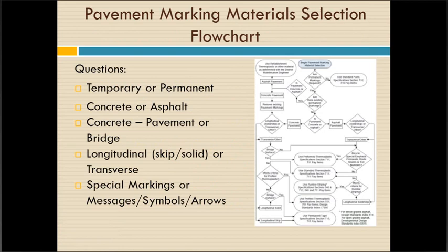But what you should always do is, if it says that the material you should be using is profile thermoplastic, you need to go to the PPM in that section on profile thermoplastic and verify that you're using it in accordance with the PPM. Now, if you find anything that you think is different, you get a different answer, please give us a call.